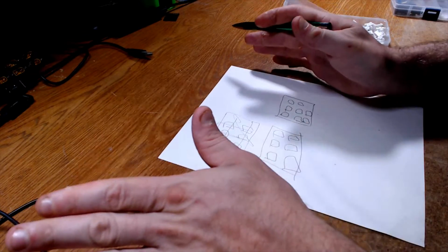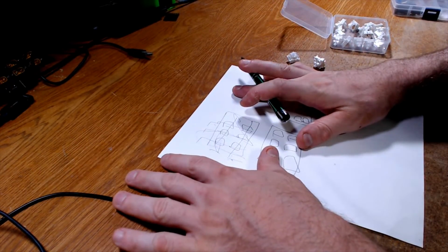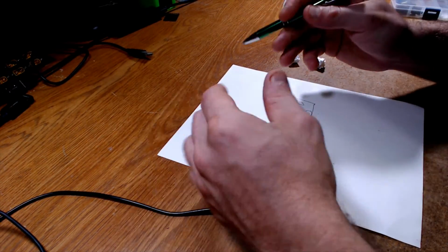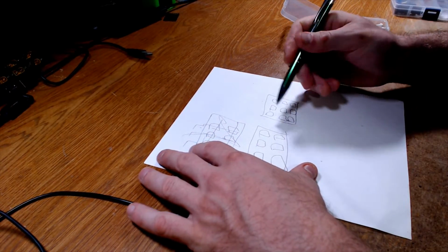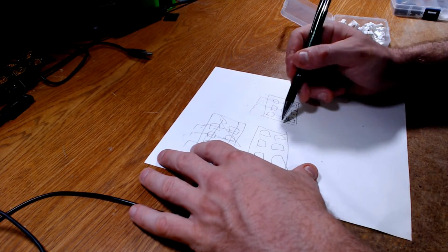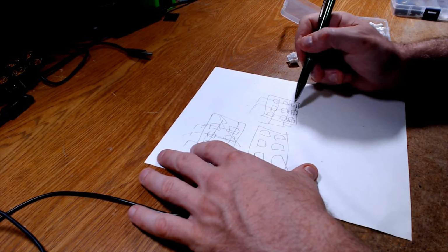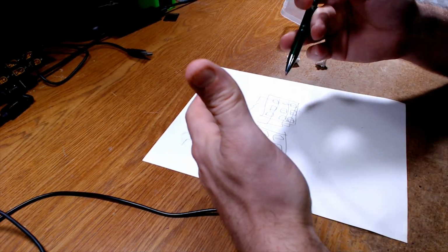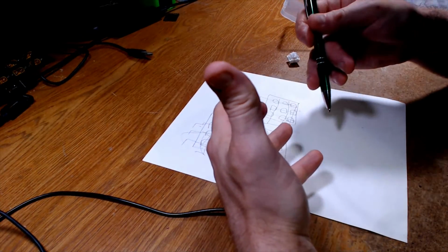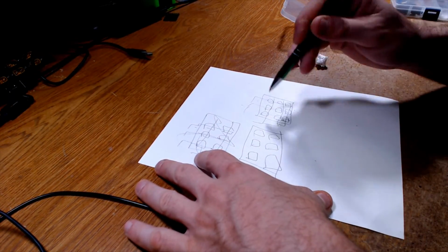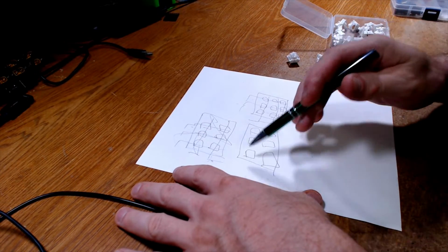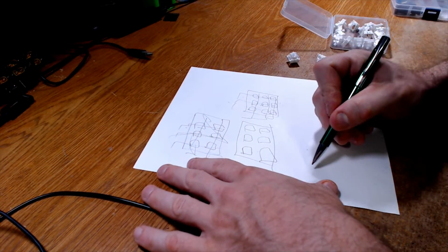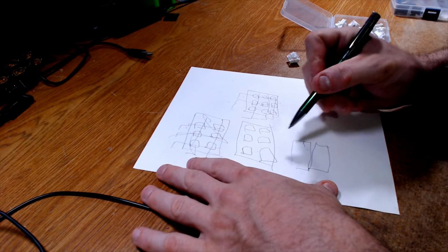My plan for today, and I didn't say this at the beginning, is that this is just a design stream. We're going to do the electronics and the coding in a separate stream, which is why I did not prepare anything, but yeah, that's multiplexing right there. So that's 6 wires controlling 9 buttons. The plan is to have the buttons multiplexed, and then the way we make it modular is by multiplexing in more buttons, and we'll get to that when we get to the electronics section. But needless to say, we'll figure out how many buttons we need on each pad, and I think we'll be going with 9, and then we're going to just stack up a whole bunch of pads is my intention.